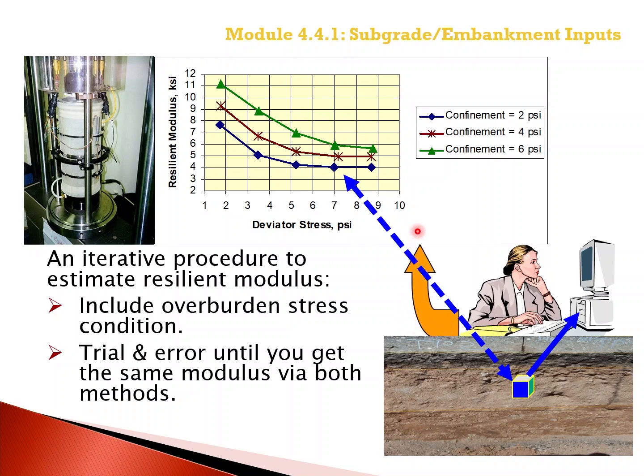That is then compared at the equivalent stress state in the laboratory, to determine if the resilient modulus selected by the user to calculate the responses, stresses and strains, is equivalent to the laboratory test strain and stress, or modulus and stress, for the modulus that was used in the initial iteration.